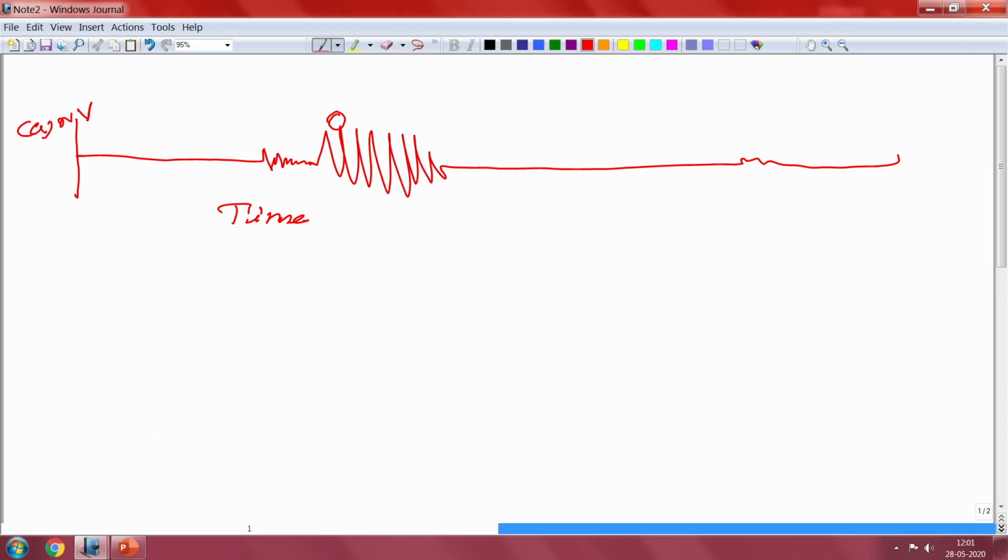The S wave is a wave where the particles vibrate perpendicular to the wave direction. Because of that, it creates a large amount of inertial force and instability in the structure, which needs to be considered for the design. So, taking the peak values is one way you can interpret the record in the time domain.